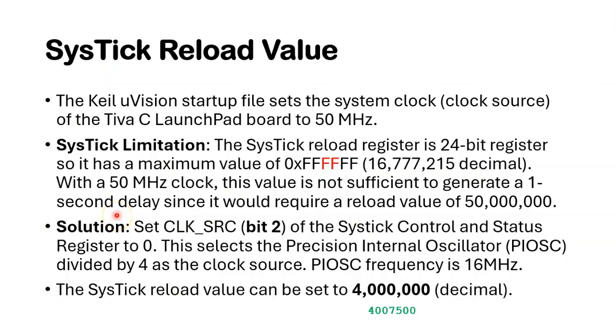So, the Keil MicroVision startup file. Now this only applies to the Keil MicroVision IDE. Other IDEs will do it differently. So the Keil MicroVision startup file sets the system clock of the TM4C LaunchPad board to 50 megahertz.